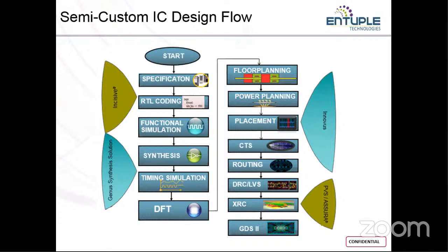For synthesis, translating your HDL into a block level or module level design, or any type of logical representation, you have the tool called Genus, and that process is called synthesis. Once you synthesize your design, you need to check for the timing, area, and power. In short, we call that TAP.